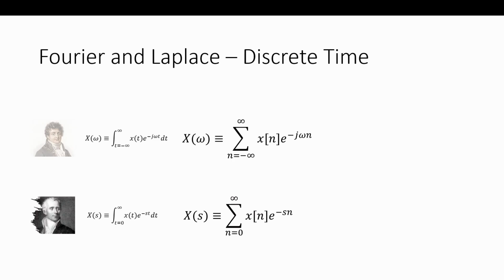That's the multiply and accumulate I was referring to. Set n, whatever n is, multiply it by this spinning phasor as we increment n. That's going to be rotating, right? Multiply it, add it up for each frequency. It's the same thing we talked about before, so integrate, summing the plots, right? And we can do that with Laplace as well.